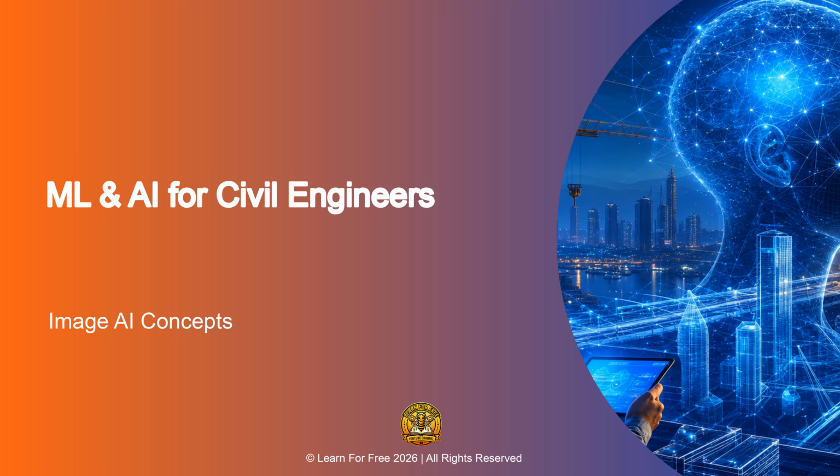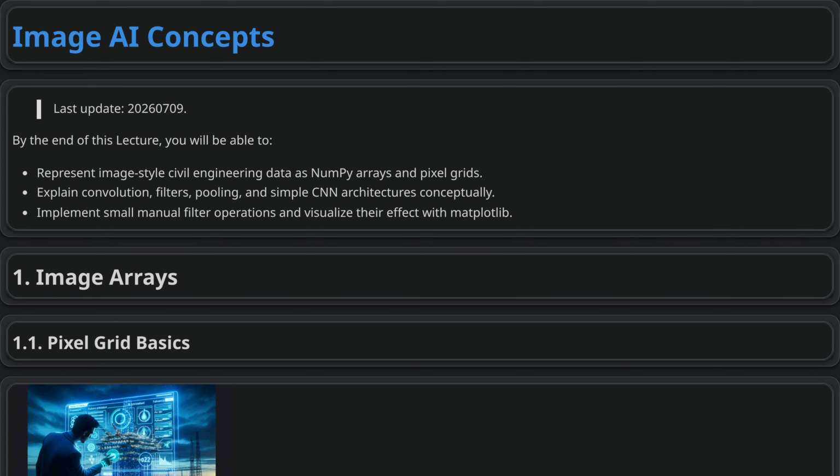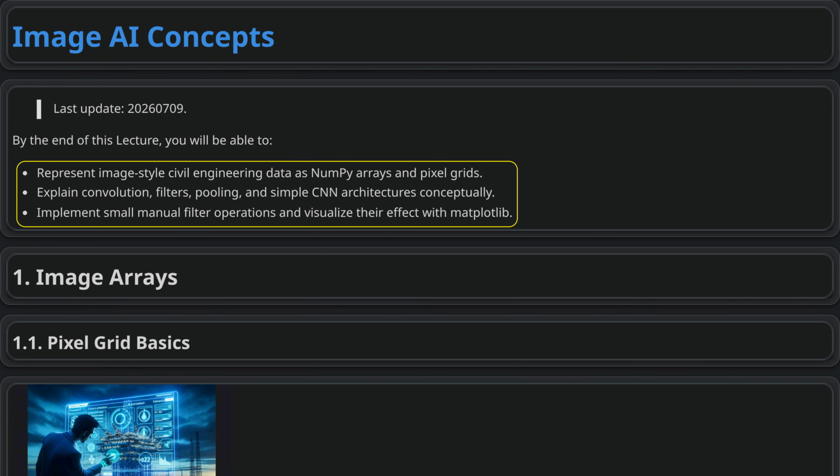Module 8, Lecture A, Image AI Concepts. By the end of this lecture, you will be able to represent image-style civil engineering data as NumPy arrays and pixel grids, explain convolution, filters, pooling, and simple CNN architectures conceptually, and implement small manual filter operations and visualize their effect with Matplotlib.